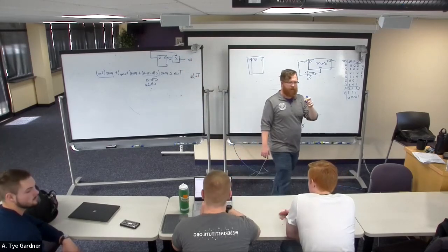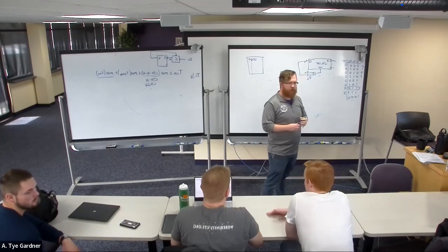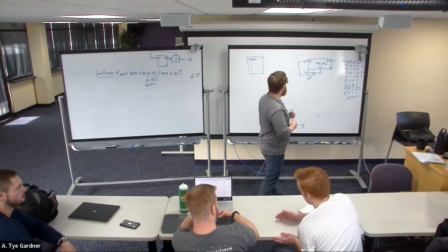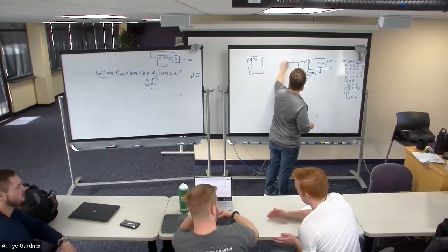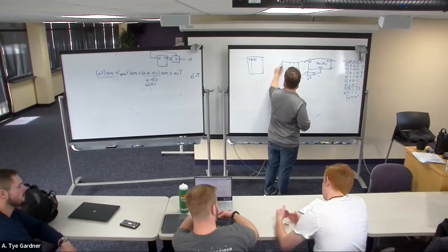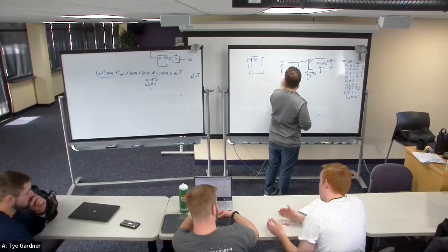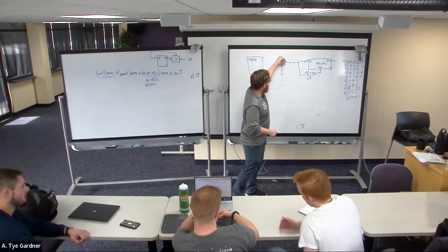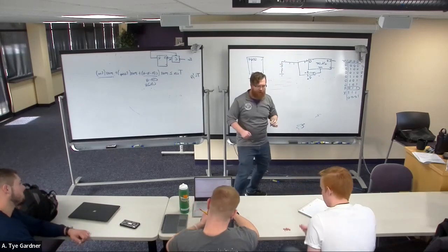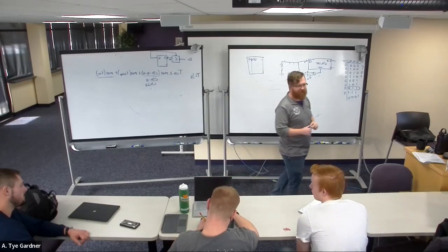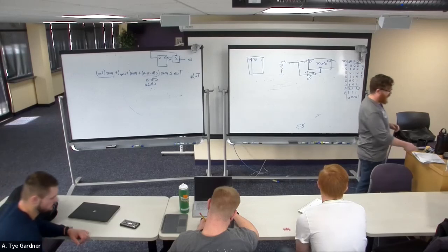Yeah, I was just going to say, so for the 3-bit counter, how would you move that up? So let's say like LEDs or something from there. So this is 3 bits. So just from right there. Each of these, LED, and to repeat. Right, where this is 1 bit, 1 pin as mapped on your FPGA through a constraint file.